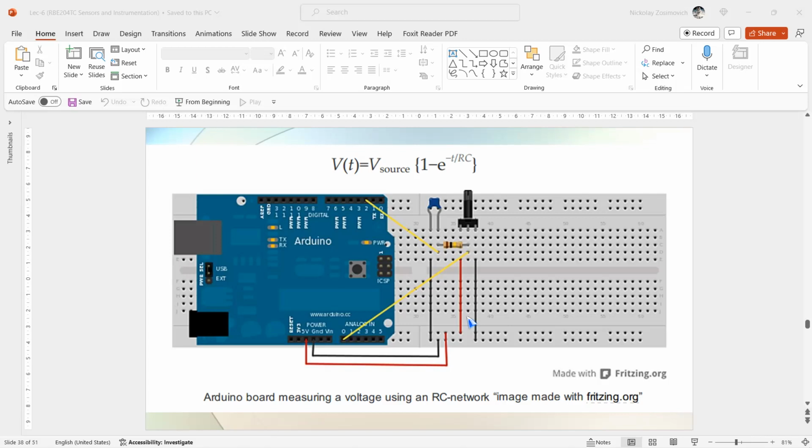In this case, the voltage is measured simultaneously with one of the analog to digital converter input pins and with the RC network connected to pin 2. By making pin 2 an output, the capacitor can be fully charged or fully discharged. After switching back to input, when we have high impedance, the capacitor will be discharged or charged, well, exponentially, so it does not matter from which position it starts, by the sensor voltage supplied by the potentiometer, acting as a position sensor here.